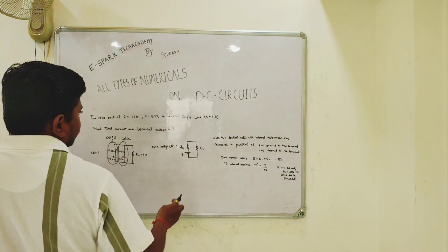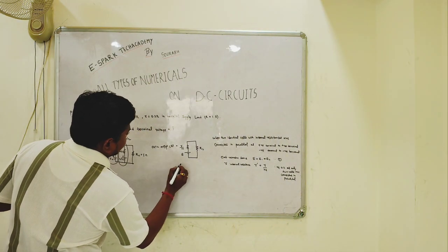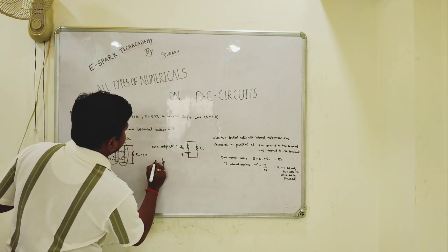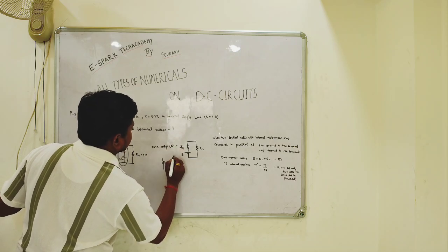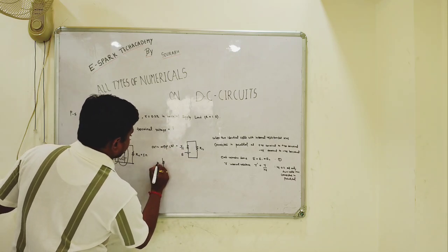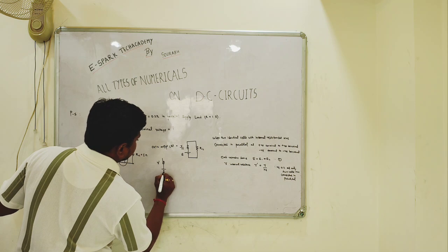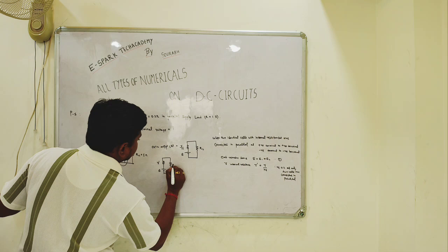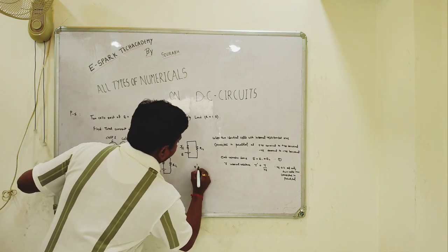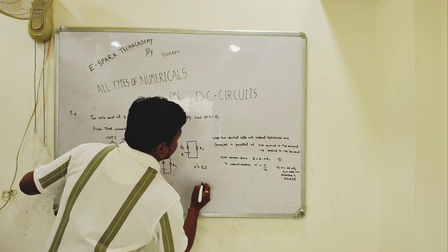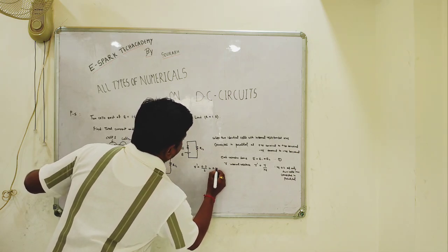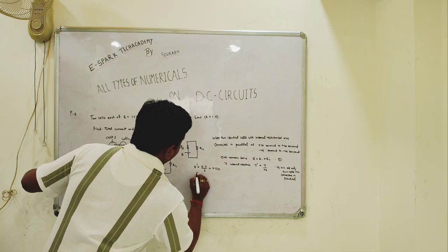So now the answer will be, the final figure will be R by N. It is nothing but 0.3, it is nothing but R dash actually. I will first write it as R dash, E, and a resistance RL, where R dash will be 0.3 divided by 2. It will be 0.15 ohm, and E is already given as 1.5 volts.